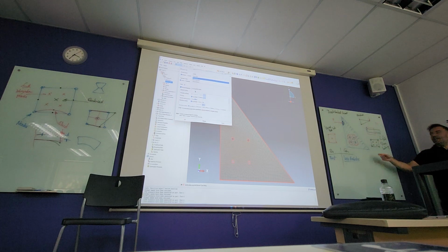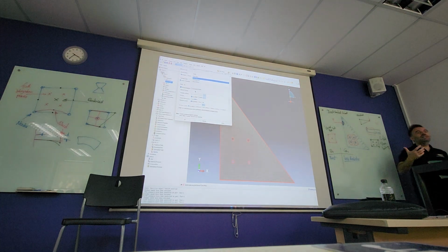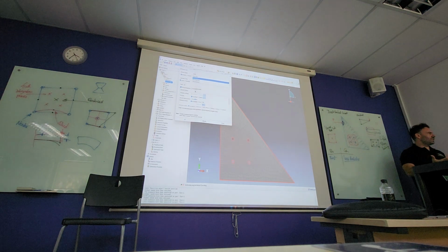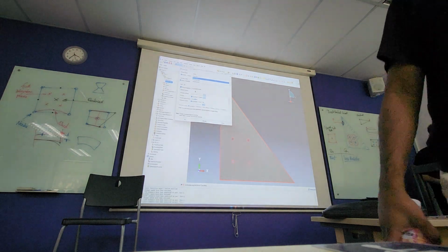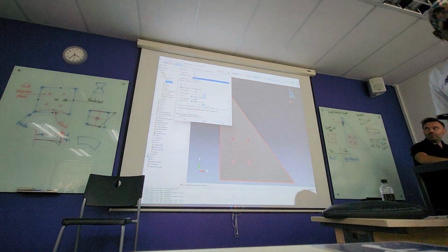But if you run an analysis, Abaqus would say, if you put 1 Newton, it's going to stay like this and would not change. It says it's much stiffer than it should be. So that's a problem with these elements. So generally, they tend to overestimate performance of your structure. Yeah? So what are the other options that we can go?